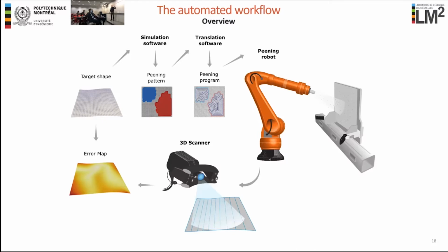Then we numerically superimpose the target shape and this numerical model of the final shape, and we obtain the error map, showing all these local discrepancies between the two shapes. And the Hausdorff distance actually is the maximal local discrepancy, which in this example is in the left bottom corner. This dark red color stands for the biggest error, the Hausdorff distance.